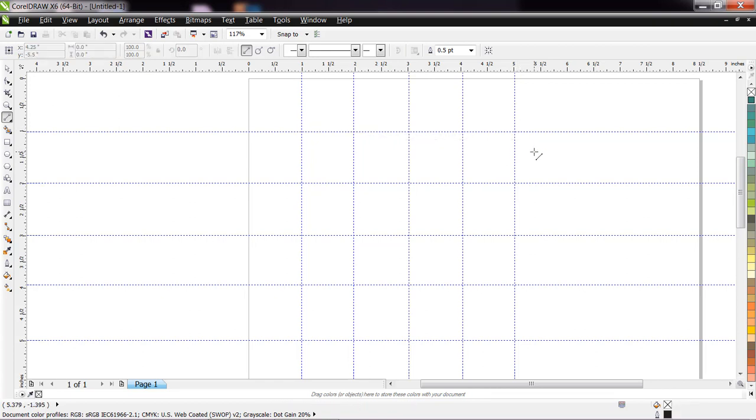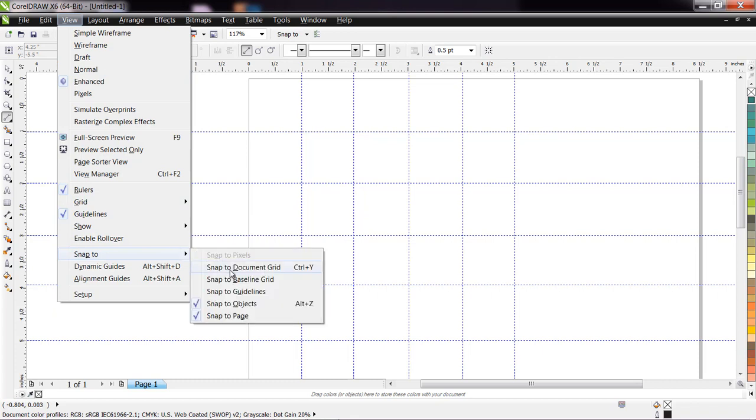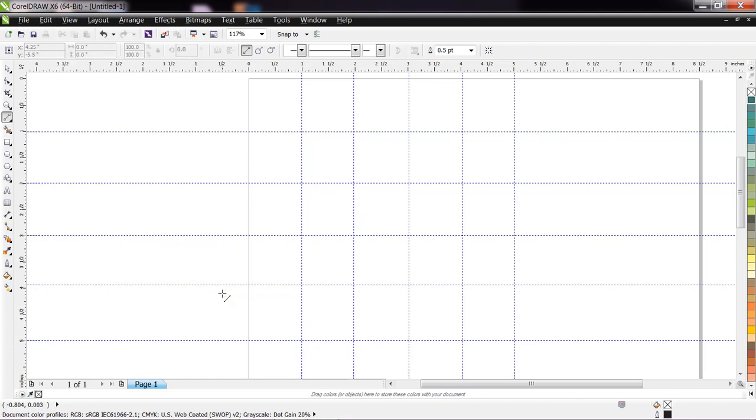Then how to draw a straight line? For that purpose here we use guideline. Therefore you have to set one more thing, that is the snapping property. Here use snap to guideline. Now click here, begin from this point and then drag your mouse to this point. This is your straight line created.